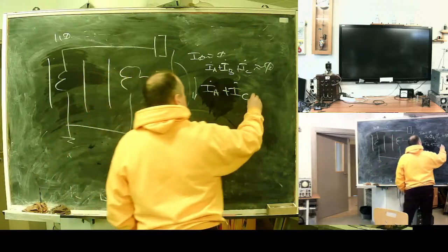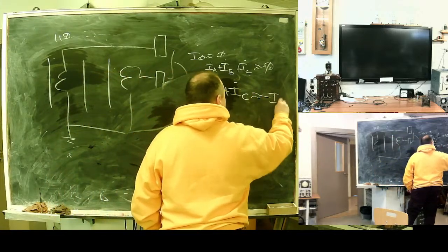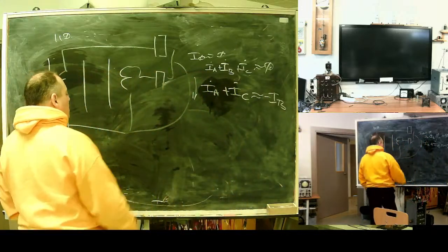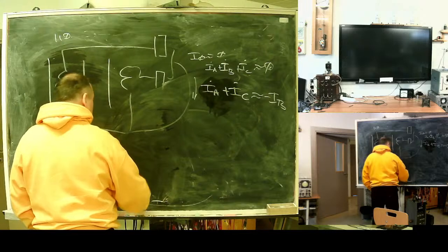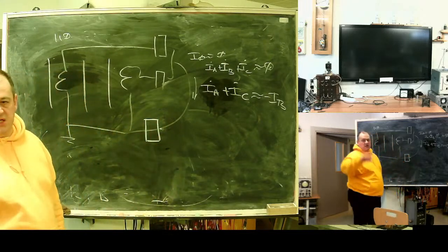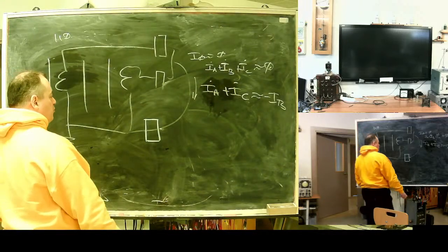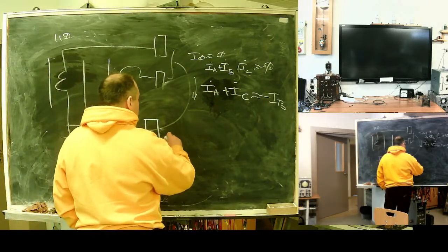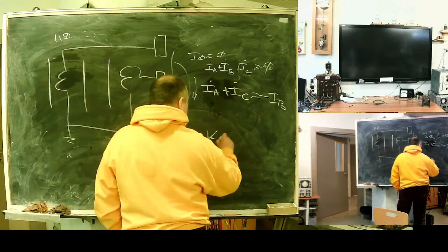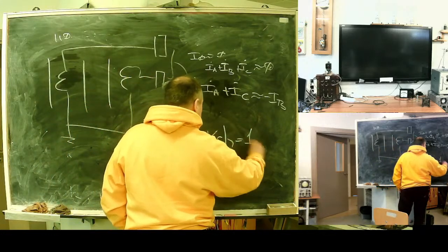So this current is approximately minus B phase current. Plant one more relay in the return wire of the incomplete star. This will sit on minus B. For this, schematic factor will be 1.